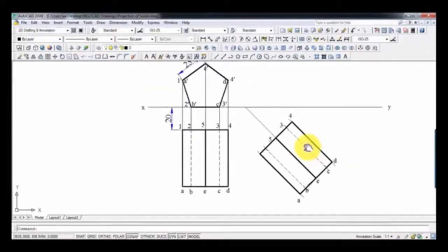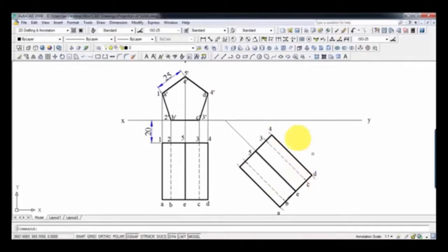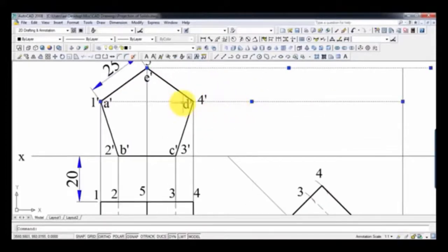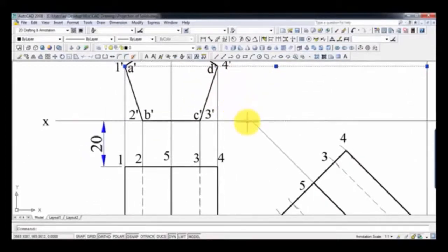Then the next thing to do is to draw vertical lines from this object over here and to draw horizontal lines towards the right. Okay, and finally these lines are going to intersect at different points. So the horizontal lines are almost done. I mean, this line accounts for 5 and E, and this line over here accounts for 4, D, 1, A, and this already drawn line, the XY line overlapping, accounts for 2, B, C, and 3. Fine.